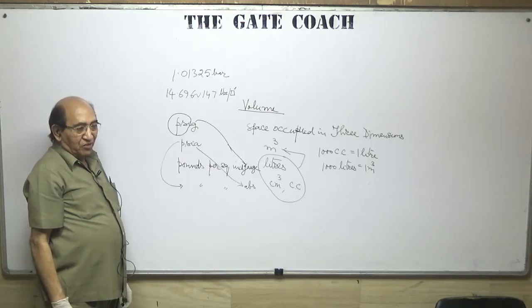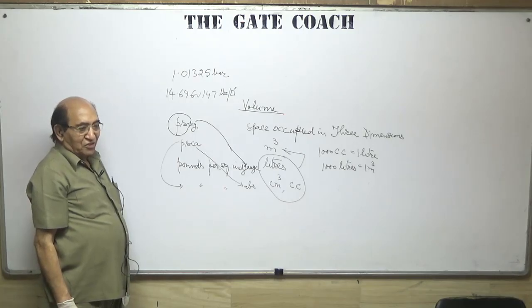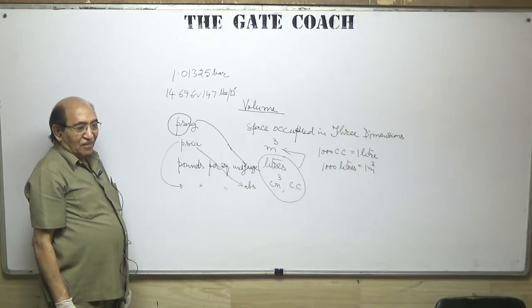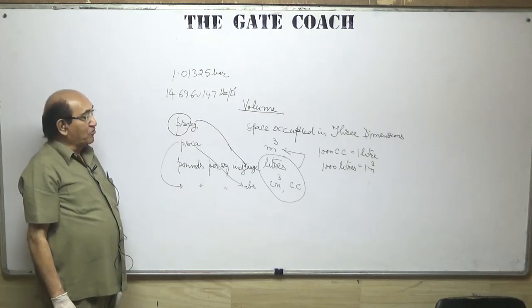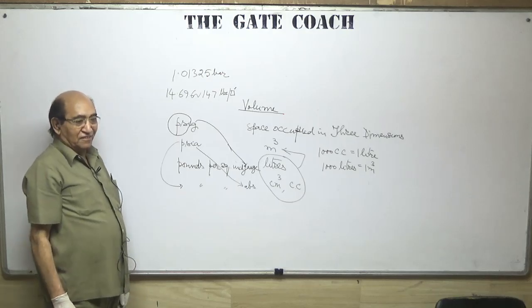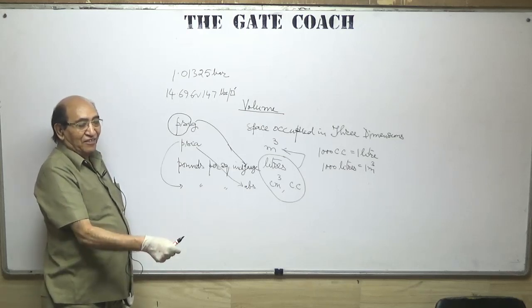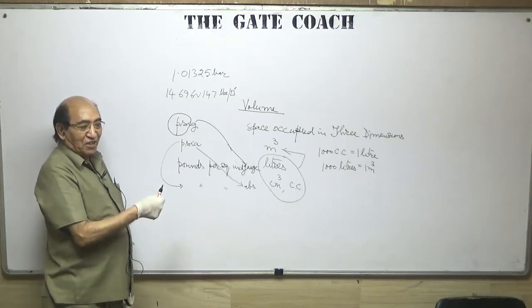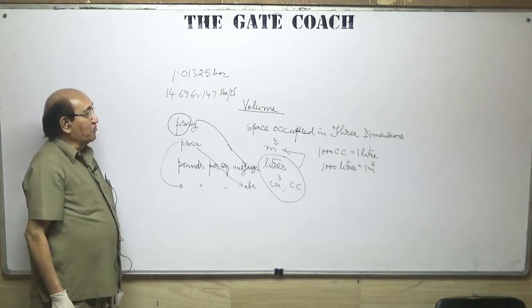When you are going to the petrol pump for taking high pressure air for your vehicle, you tell him, 28-28 कर दो, 25-25 कर दो. वो 25 क्या था? That was pound per square inch gauge. The gauge which he is using should read that value as gauge pressure in terms of pounds per square inch. This used to be in FPS system.